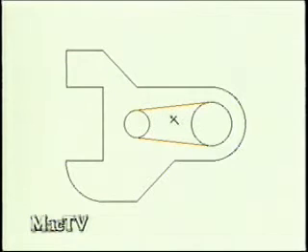Then using these two lines as the boundaries of a trim, I can cut off those two to get a nice tapered slot. So drawing this part is a real good example of how to use the Drafting Assistant and how fast it makes drawing a part like this and how precise you can be with your sketching.